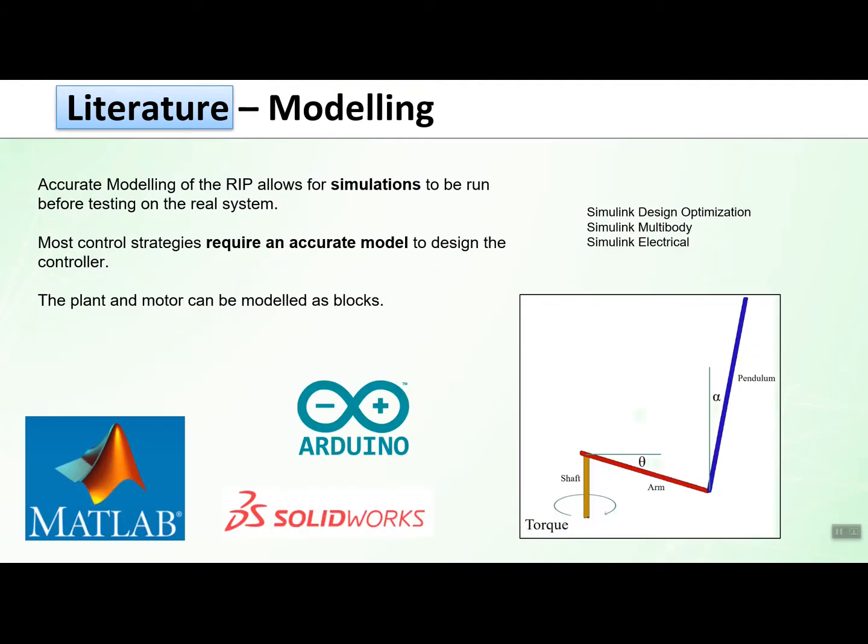Onto the modeling section then. Typically a model of the physical system is simulated with the controller of choice before testing on the actual rotary inverted pendulum rig. Most control strategies require an accurate model, but not all. For example, fuzzy control does not require an accurate model, and PID does not require a model at all.